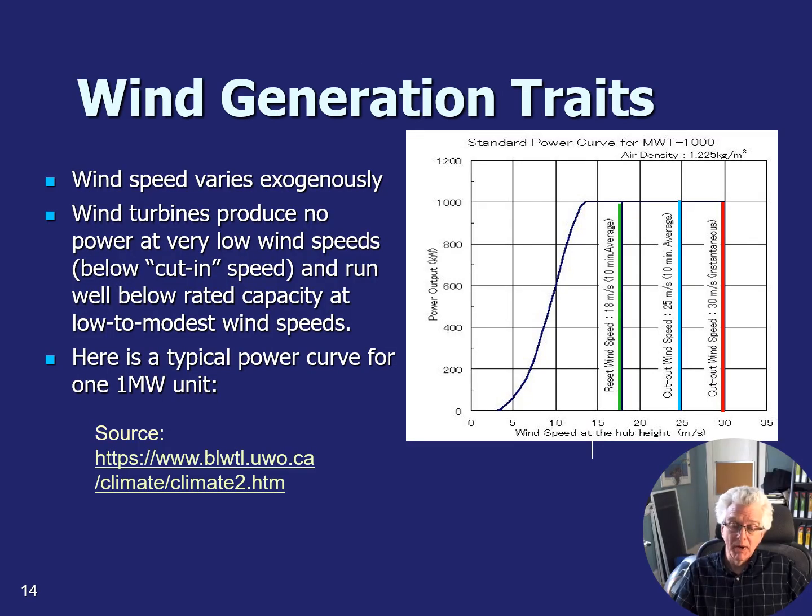So this is a diagram I made up, and there's a similar one, perhaps just as clear, maybe easier to understand in the AHO article, so please have a look there. If you look at the characteristics of what a wind turbine can provide, based on the varying wind speed, there's a ramp up input as the wind comes off. There's no output when the wind is at 4 meters per second, and then as it gets higher, you ramp up in an S curve until you reach the peak output, the design capacity of the turbine.